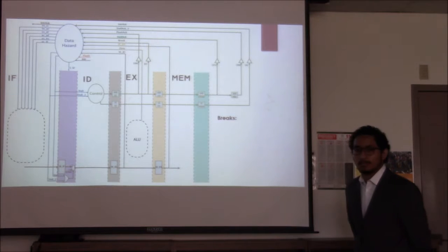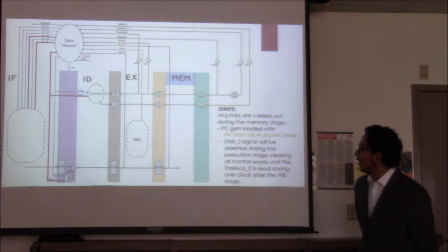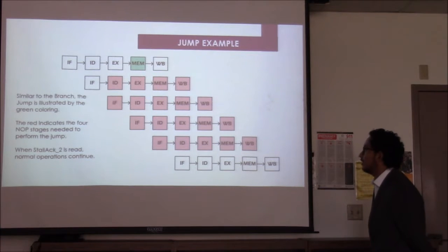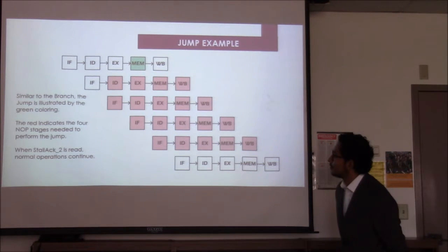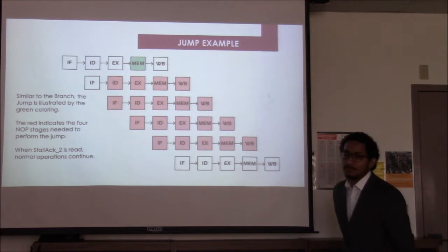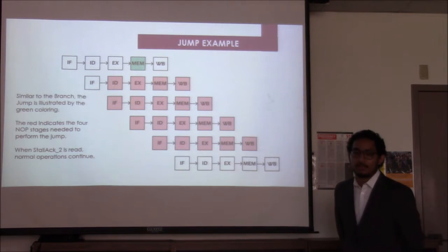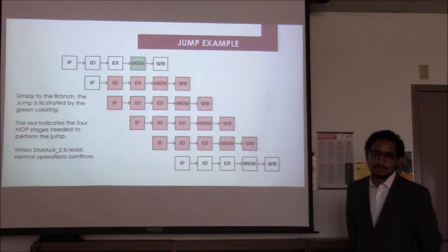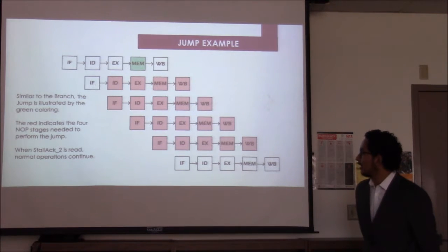Are you going to explain why it took so many stalls? Yeah, so technically, since we are jumping in the memory stage, we decided to do all of our 3 jumps in the memory stage just for sake of simplicity. Some jumps can be done in the instruction decode stage, but we just decided to do everything in the memory stage.